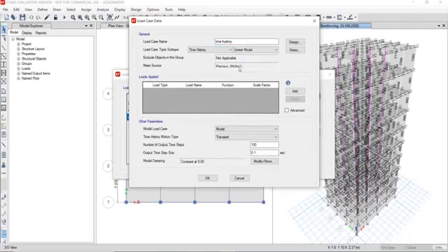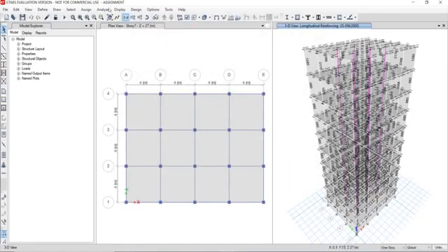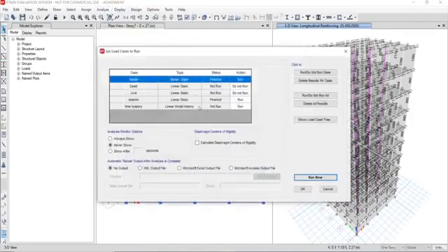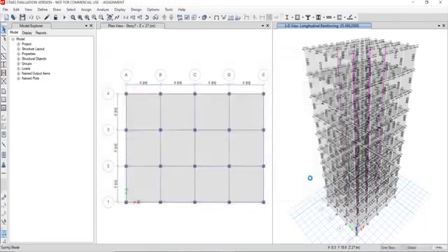Go for time history analysis. Add our load applied in acceleration load type and its load name is U1 and function is our given time history function and scale factor is 1633.5. We already saw that we only have X direction, so no need to add another load case. Then click OK. Click OK. Now analyze, set load cases to analyze, as in the previous type. Now click run now.